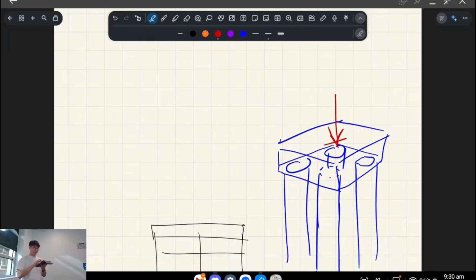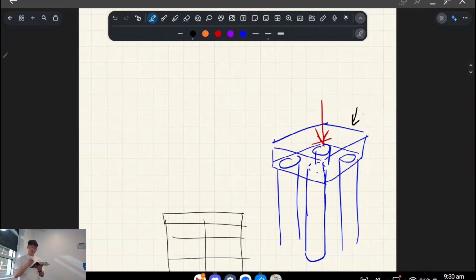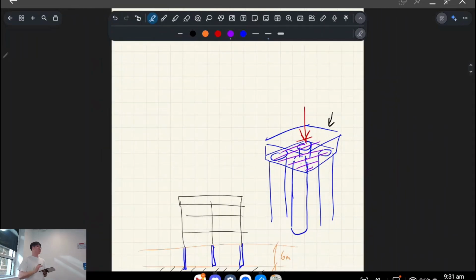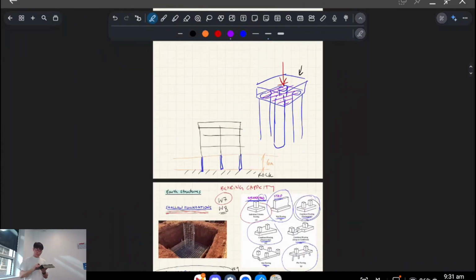So there are many reasons why you might have a pile cap, but a pile cap is not the same thing as a pad footing, because it's mostly to transfer loads from a column into the piles, rather than relying on the bearing pressure here. I'm not going to talk too much more about that. Hopefully that gives you a summary of why you might see pile caps.